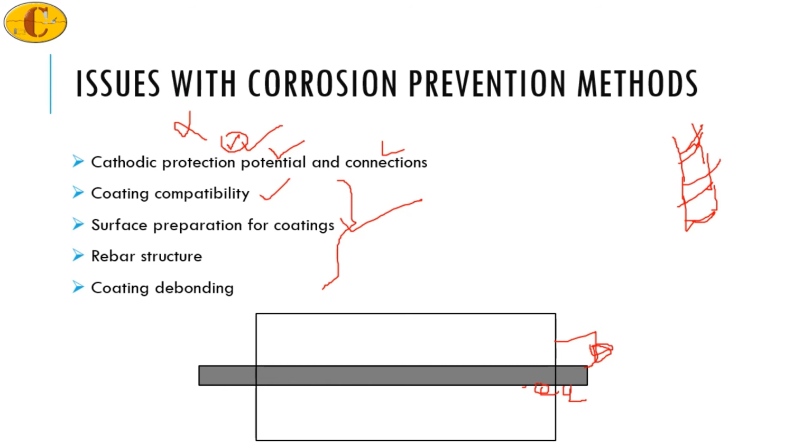So the surface preparation is not always done, because that may destroy the threads as well. If the surface preparation is done on the flat parts, then the edges or the nooks near the threads remain unprepared all the time, so the coating adhesion may not be really good.